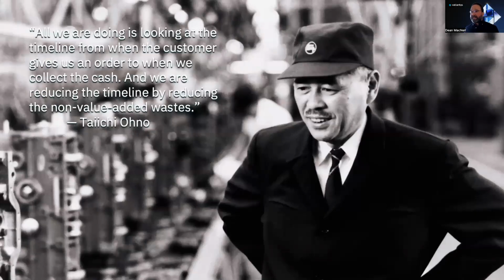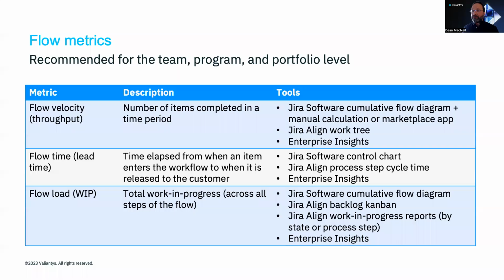Value streams help identify the flow of value and recognize the non-value added waste, or muda in Japanese. What is now known as value stream mapping, thanks to the 1998 Learning to See workbook by Shook and Rother, has its origins in Toyota's Materials and Information Flow Analysis. This looks at the timeline from customer order to receipt of cash and shortens the timeline by reducing waste, which brings us to measuring flow.